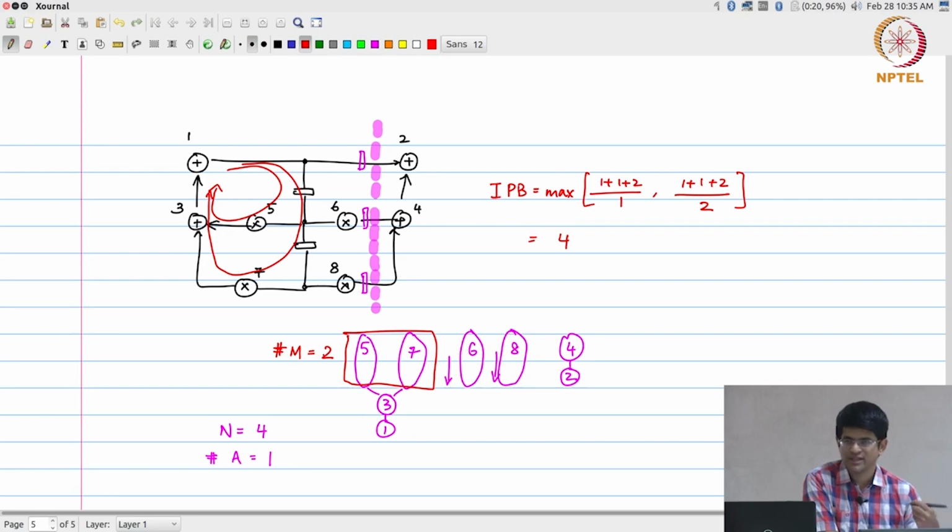So you see the procedure that I am following, right. I essentially started off with a critical path of 5 time units, right. Obviously that was more than required. I know that there is a fairly straightforward way by which I can bring it down to 4 time units, and the shorter the better in general, okay. So once I have brought it down to 4 time units, I can then think of the best possible hardware allocation that I can get away with, right. In this case, the reduction of critical path to 4 time units was easy. I just applied a pipelining along that magenta line over there, the dashed line, okay. That achieved that purpose at least.